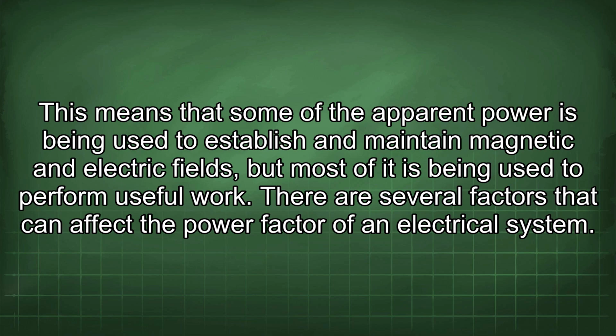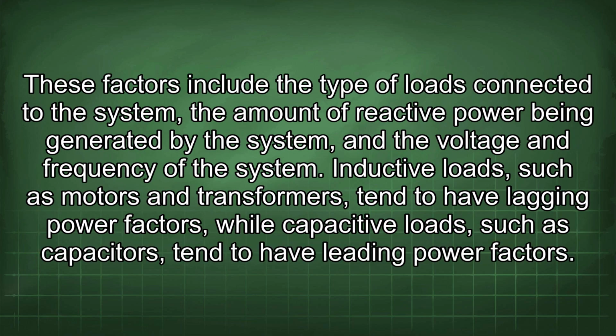There are several factors that can affect the power factor of an electrical system. These factors include the type of loads connected to the system, the amount of reactive power being generated by the system, and the voltage and frequency of the system. Inductive loads, such as motors and transformers, tend to have lagging power factors, while capacitive loads, such as capacitors, tend to have leading power factors.